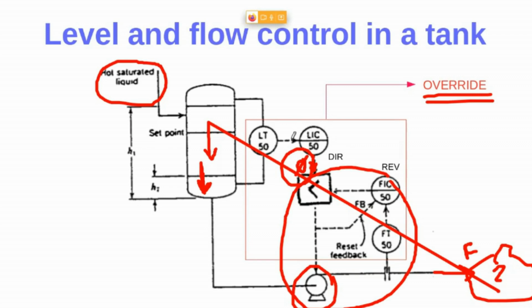Well, this level controller is configured with a direct controller action, just because if you increase the power applied to this pump, the level decreases, right? So we have a negative relationship between the input of the process, that is to apply an increasing signal here to the pump, and the output, that is the level measurement in here, which decreases. So that's why we use direct controller action.